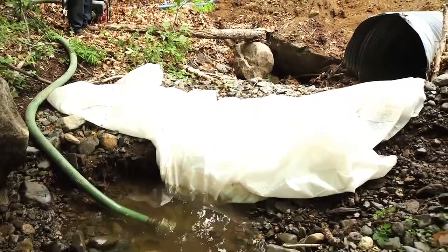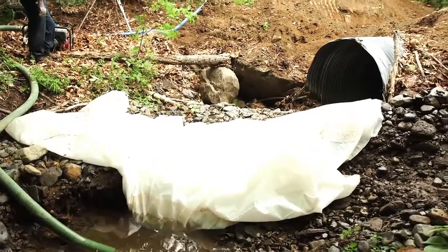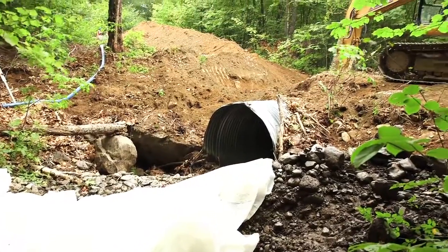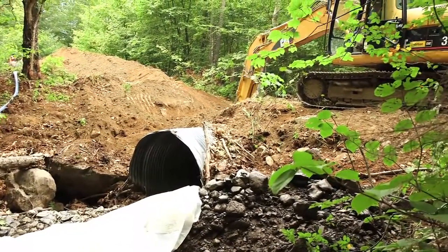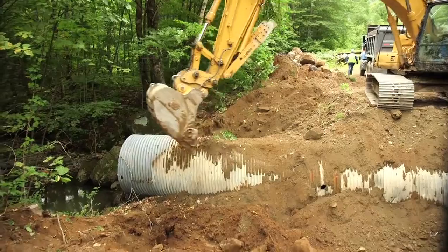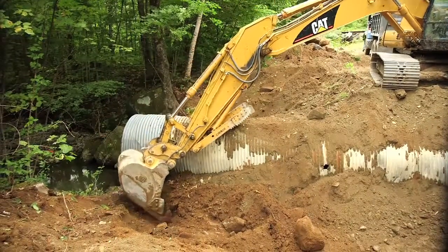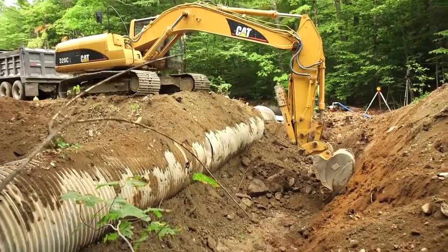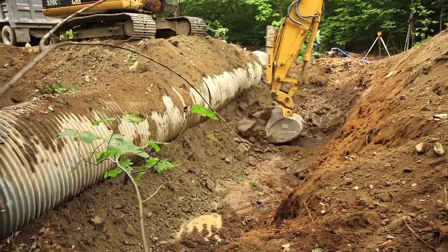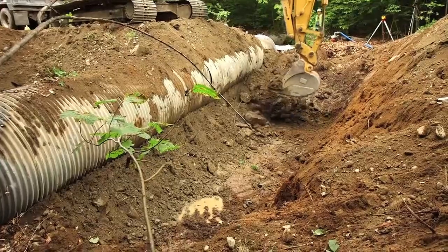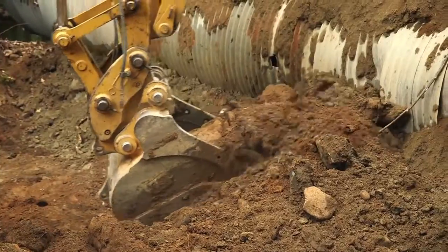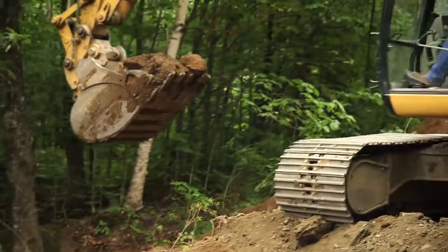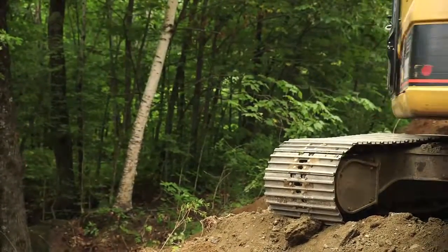Here, the dewatering has been initiated since the excavation is getting closer to the stream. All flow through the pipe has been stopped and is now being pumped around the work area. The pipe is left in place to allow for a working area for the excavator to install the far side abutments. This is important as there is only one excavator on site, so all work has to be done from one side. On larger sites, an excavator may be needed on both sides since all of the work area cannot be accessed from one side.